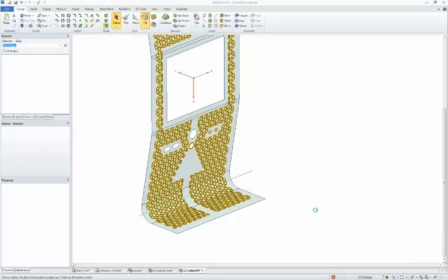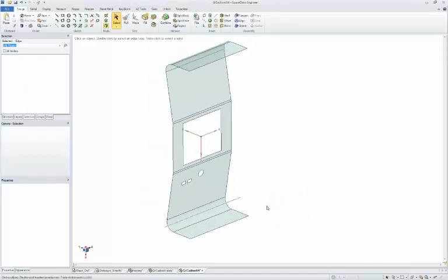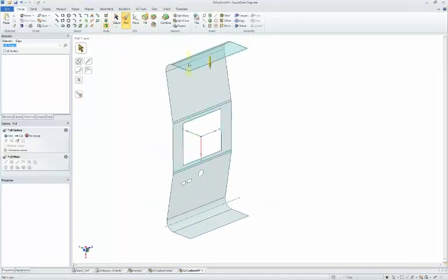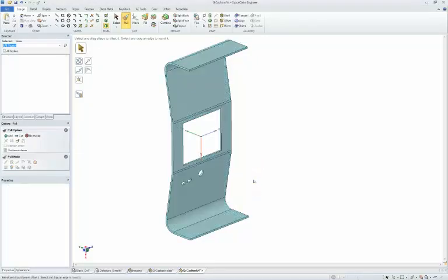on this design. That's a lot of complexity, which, for some analyses, is up to you. You may want to keep it and just have your mesh chug and chug and chug. Other times, to do a faster analysis, get rid of that. Now that we have the thin surface all cleaned up, all 6,000 edges were removed, we can thicken this to whatever thickness that initially was.